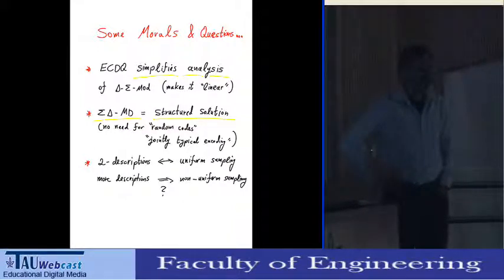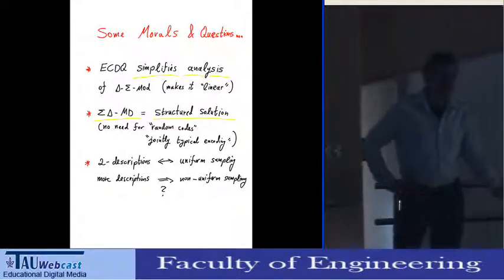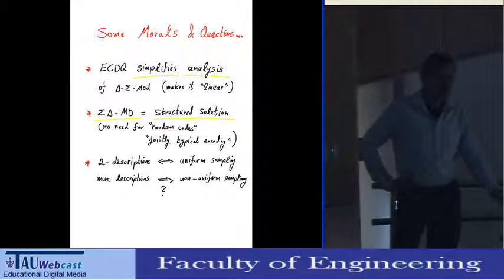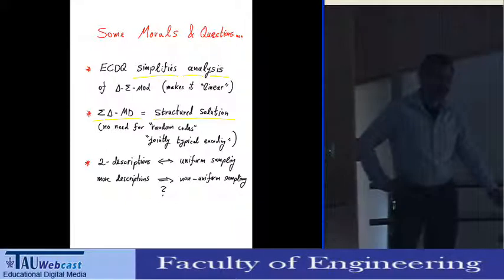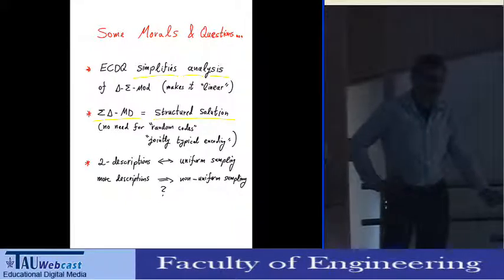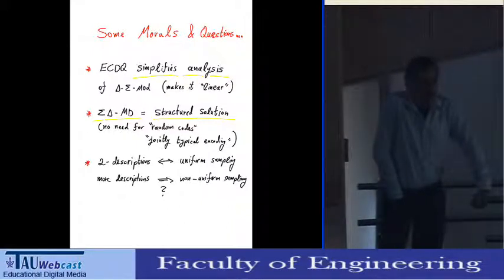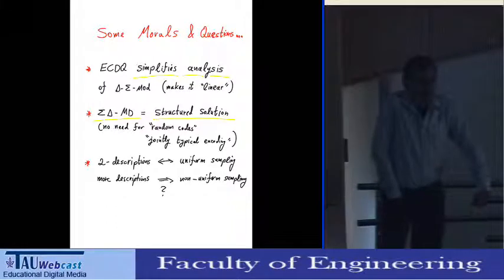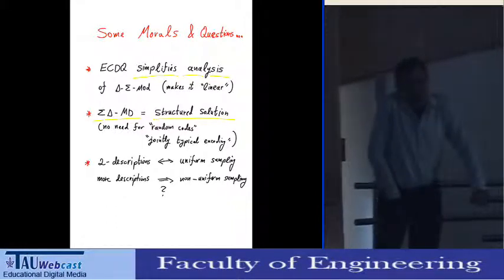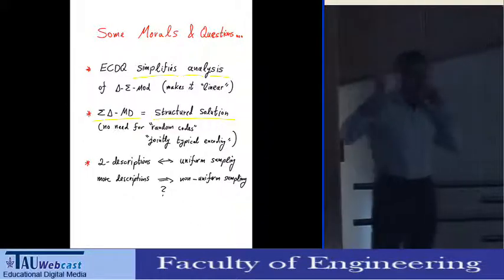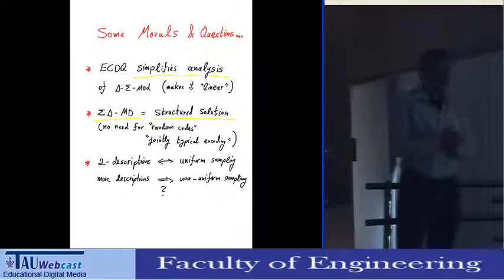I see that the trade-off between the sample distortion and the side distortion comes from the filter choice. You try to sort of trade off between the noise shaping outside the band and what happens when it's aliased inside. But you presented some solution, how sensitive is it? I mean, how accurate do you have to make those filters in order really to get what you promised us? Because in order to get the 2-step, you need the infinite order filter. Usually you use filters.